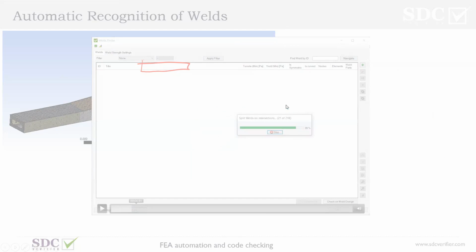No, but my question is, could the model assume welds where on the real crane they do not exist, because the crane manufacturer does not put any weld in that place? Exactly. It can, because we can tell the software to do that. So that's what I meant. Most of the things are automatically recognized if they exist. If something does not exist because the manufacturer forgot to put it, but we know that it's there, we can add it manually. I can say to the software, please take this additional weld into account, which is over here, and it will be accounted for.